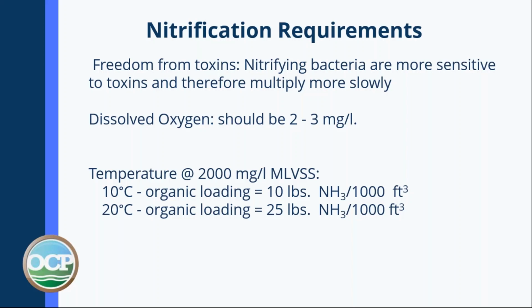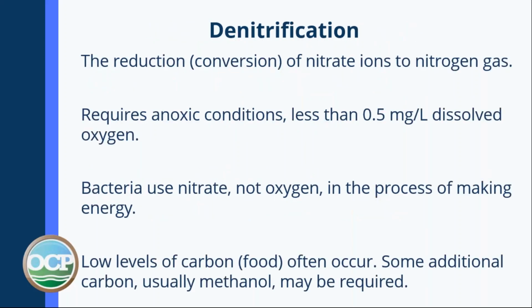Denitrification is the reduction or conversion of nitrate ions to nitrogen gas. This requires anoxic conditions in your tank. That's less than 0.5 milligrams per liter dissolved oxygen, but not 0. The bacteria use nitrate, not oxygen, in the process of making energy.